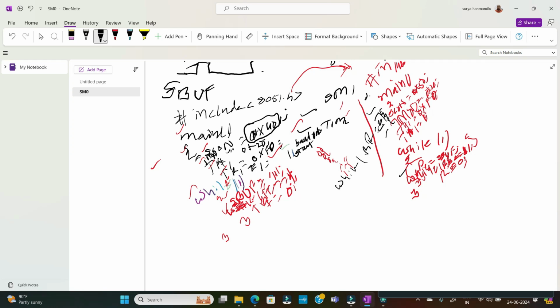Whenever it becomes 1, data is received into SBUF. Whatever data is received into SBUF, we have to keep it in P1. As I said, this statement should come up and the P1 statement should come down. Then immediately you have to clear RI equal to 0. I wrote only R here, but it is RI, capital RI. Always you have to write registers in capital. Now we will switch to the simulation part.